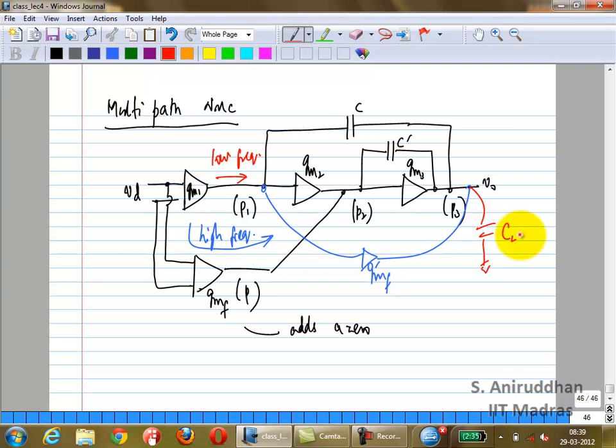Actually, right now we are assuming that GM by itself does not have any poles at all. We have not even looked at the differential pair, which has its own mirror pole. We never considered all that. We are just assuming that at all the output points, you have a pole. So if you add anything across just the first stage alone, it's just increasing the GM, nothing else.